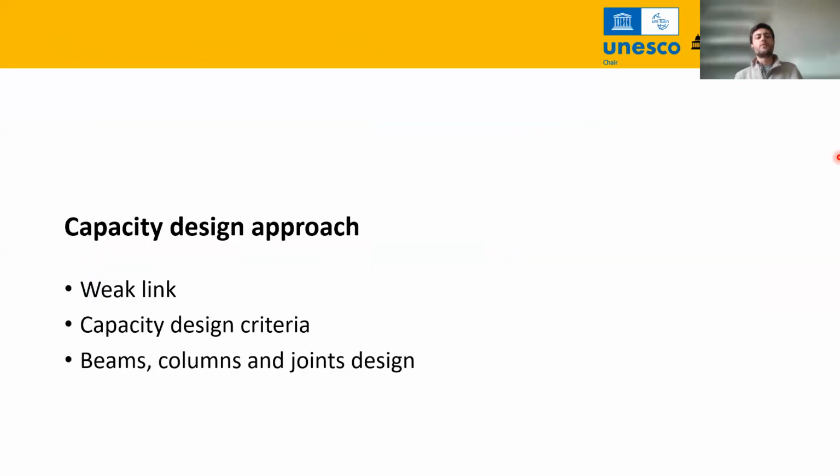So now we have understood the different types of structural systems. We go from bare frames. Usually we design the buildings to behave as bare frames. We also saw how the infills will affect the buildings, and after that we saw how these buildings can be built with some shear walls or any other stiffening element. And finally, we saw that the GLOSSI approach also includes a non-engineered structural system that is also commonly found all around the world and mainly in some rural areas.